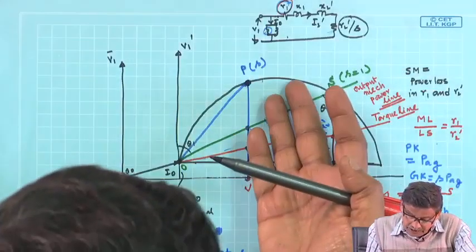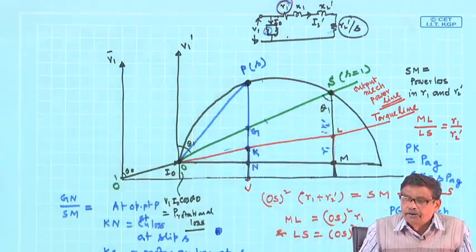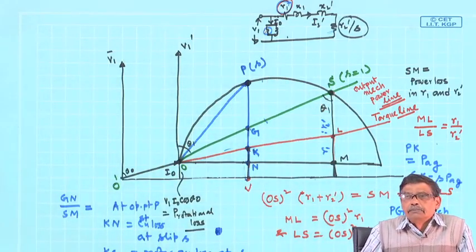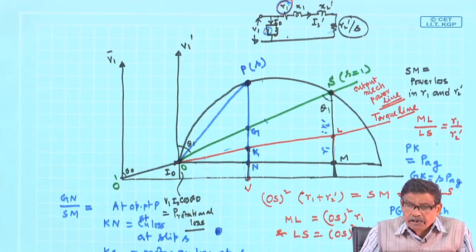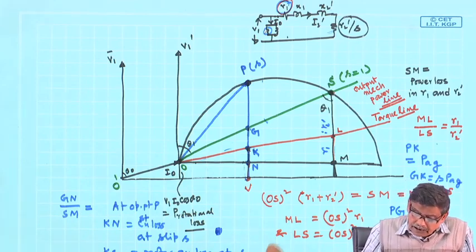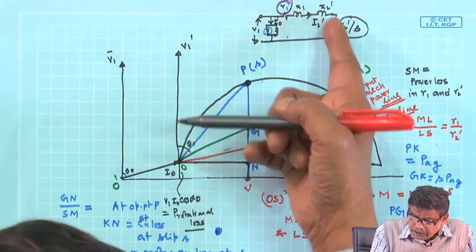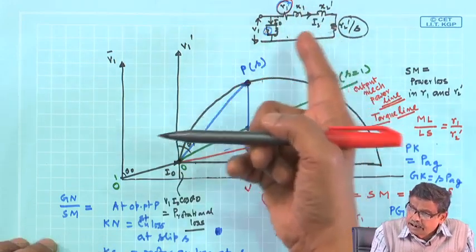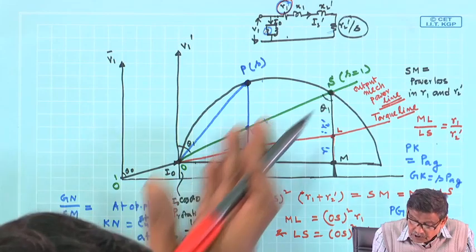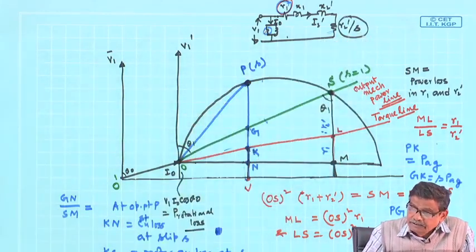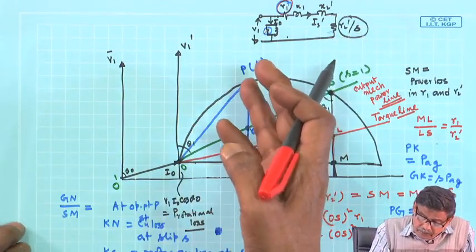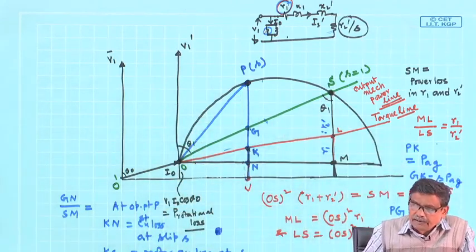Similarly, here, how do I fix up the operating point? Suppose I say slip is equal to 0.039. Then what do I have to do? You will ask for the parameter values, calculate tan inverse of that to fix up the operating point, and then once you fix it up, that is fine.